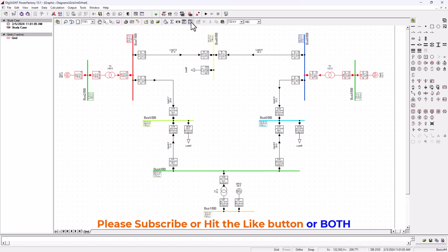Okay, let's bring in the coloring here. Now you can see that we've got an inactive bus bar, that is the slack bus here. Okay, and the areas with red, that's obviously where there are problems. So the loading is basically showing us how the buses are loaded. Green is good for us. Green basically means the voltage is good, and blue means the voltage is slightly below, and if it's red, it's slightly over. And the loading is also ranging from red to orange there.